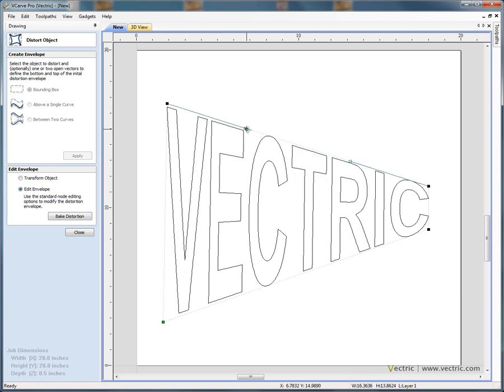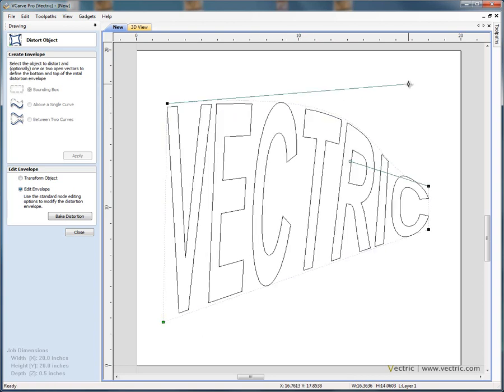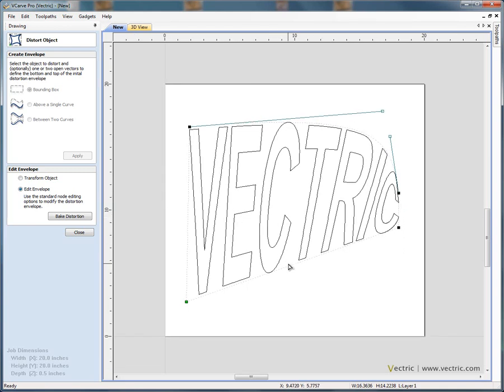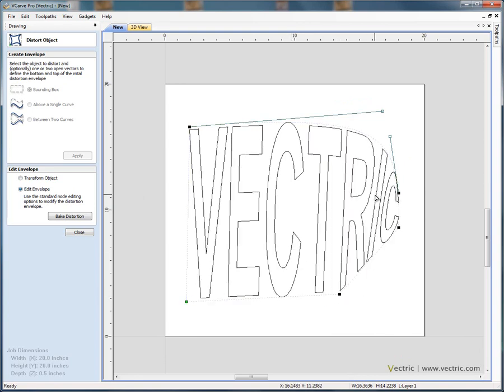When it's converted to a bezier curve, we've got some extra control, so we can change the handles, and we can make the text look as if it's sort of leaning over to the right. Very easy to work with. Again, on the bottom curve we could say insert a point, so right-click, insert a new node or point, and we can pull these lines apart like so.